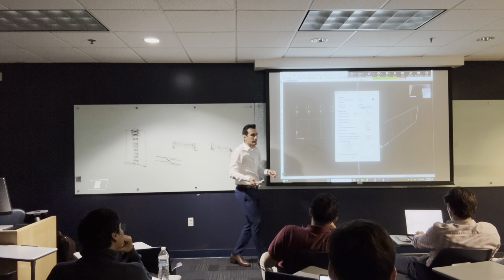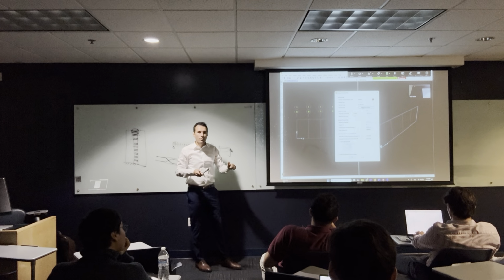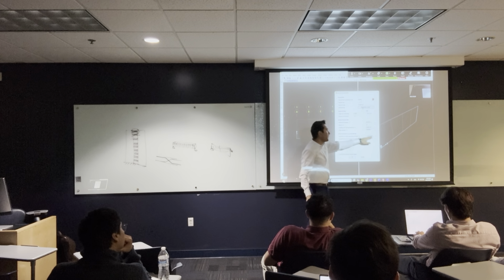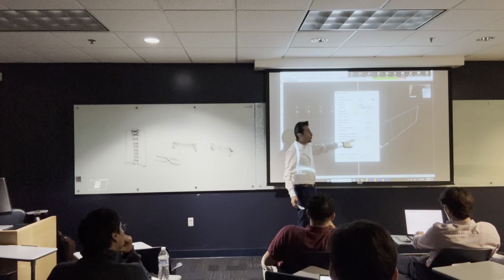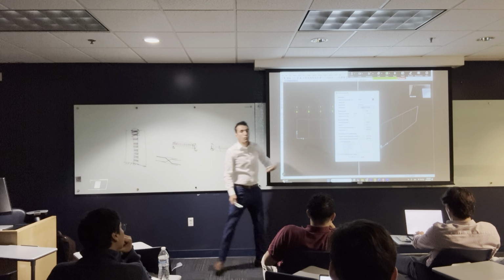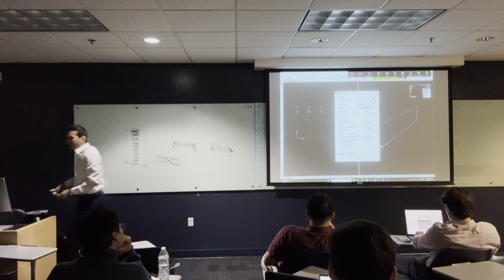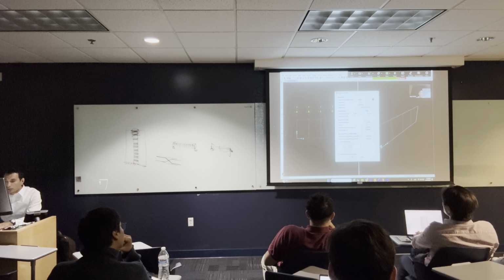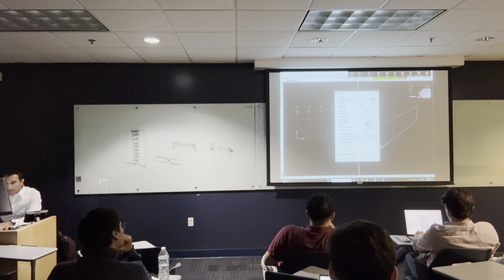We talked about it last time. When you have a truck of concrete coming to the site, we take samples, we break them, and we get the mean and standard deviation of the concrete compressive stress, and you can put it here. So that's most of the information in any material. I'm not going to change it. I'm going to keep it and use it the way it is. But if you want to change it, you can. I'm going to keep this 4,000 per square inch.